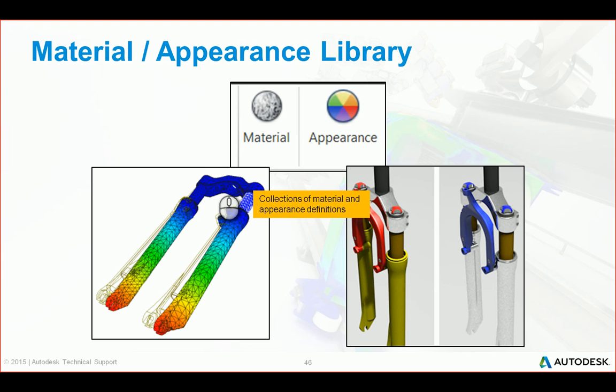So if you created a bar, let's say 1 inch round and a foot long, you could say wood, oak, or it could be aluminum, it could be stainless steel. Doesn't matter. But then we can have an appearance override on it, and we really want this to be red rather than just plain aluminum. So it would be like painting the aluminum.